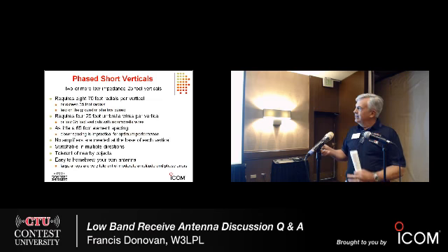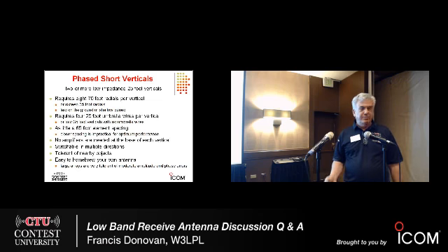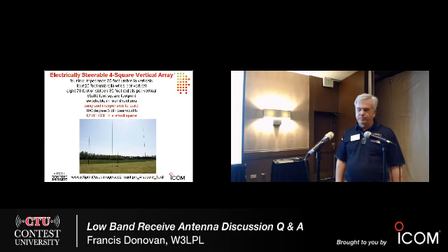So there are kind of 2 choices here. Low impedance antennas with a small number of radials, no amplifier, very tolerant of nearby objects, easy to build, no need to purchase preamps. The cost of the system is significantly less. So you have to decide which works best for you. So let's look at a couple of arrays.